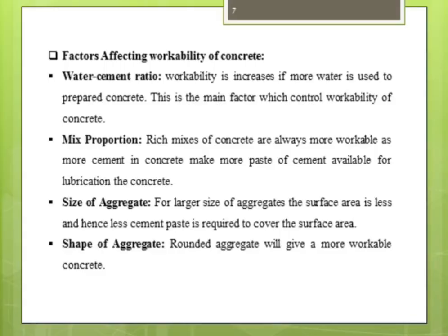Then mix proportion. If your mix proportion is not proper, you will not get workability. For example, if you are using more finer particles in your mix design, finer particle in the sense sand content, then its effect will be on the workability. How?